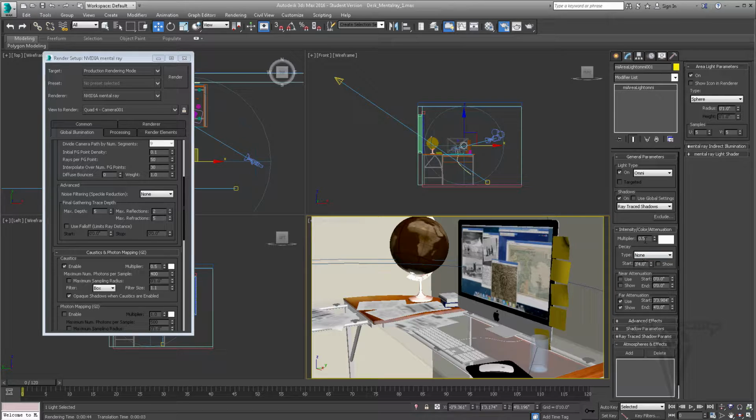Let's go to the light settings. Probably bring this center light down to 0.3. Actually, I'm going to go 0.1, way down. Let's see, area light parameters, mental ray. Is there anything else I need to? So I can actually control caustic photons from this actual light by playing with it here. I'm going to leave it alone. I'm going to leave automatically calculate energy photons checked. And go ahead and minimize this.